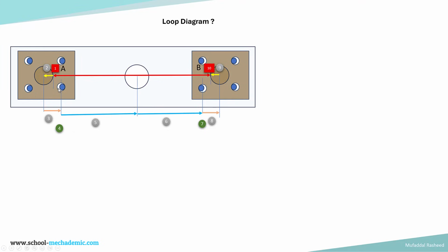So that specification we had seen 9 plus or minus 0.1. So that is accounted over here in specification number 3, which is basically the deviation in position of the post with respect to the hole over here. The deviation in position of the post. That is specification number 3.